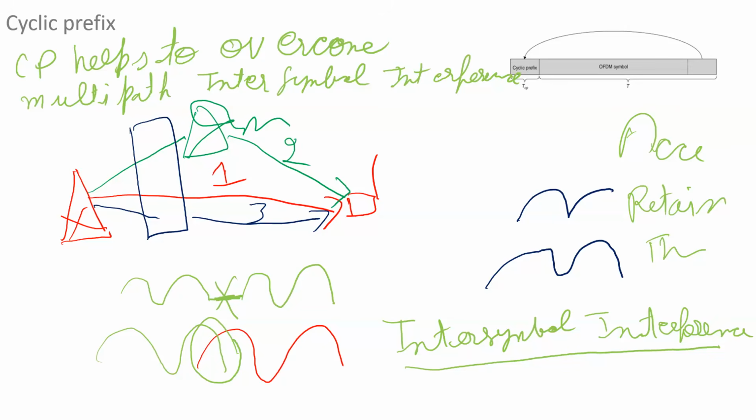So again, you can get direct signals and you can get reflections of some signals. I sent out a signal, and on the receive side, you get a direct signal and reflected copies of all these signals from the multipath. If I send a new signal and look at the multipath, it is interfering with my next signal. But think what will happen if the next signal comes after some delay. If there is some wait time between two symbols, then there are fewer chances of interference.